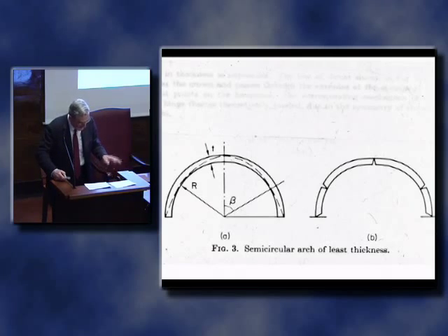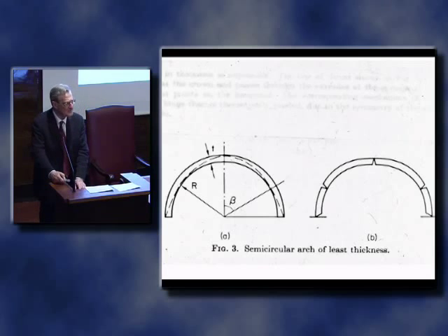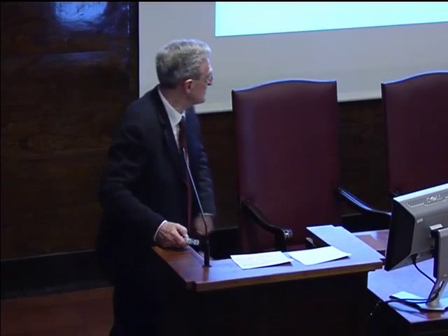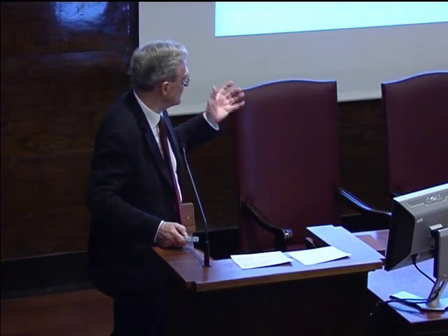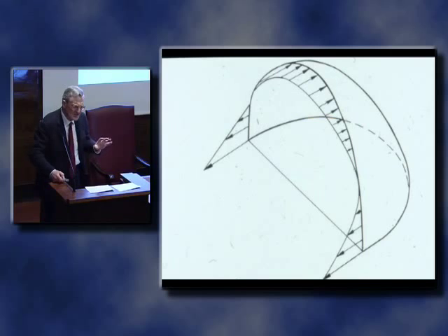Let us now get back, having had that little brief introduction to something that I'm sure you very well know about the behavior of masonry, to the shell structure, the membrane analysis, and let's consider the dome, the hemispherical dome, and apply our master equation to a pure sphere of that sort. Of course, the equation is grossly simplified if you've got the simple geometry of a sphere, and the solution comes out very, very easily and quickly.